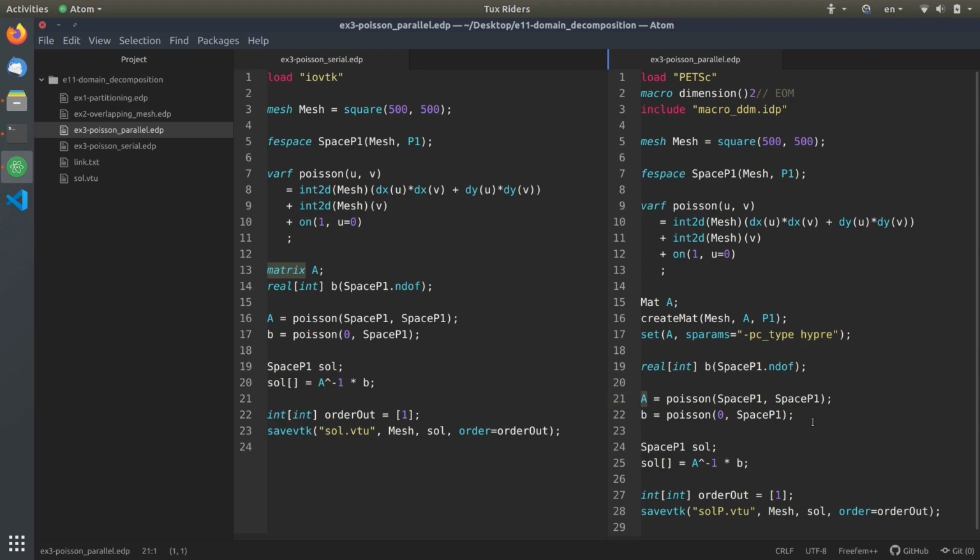And now we know, with the things that we discussed in the previous video, we are running this with parallel computing things and MPI. And this is actually a partitioned mesh. So A and B are computed separately, or let's say individually for each partition. So each CPU core will have its own A and B, and when it solves, each CPU core has its own solution, in this case, computed, and then we can have them saved into different VTU files, and this is also kind of parallel visualization or post-processing.